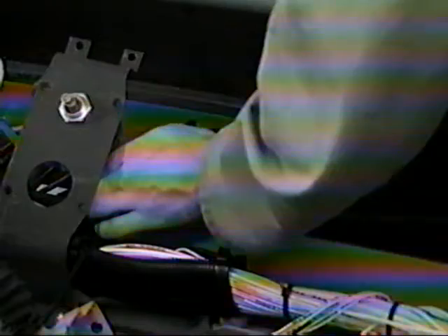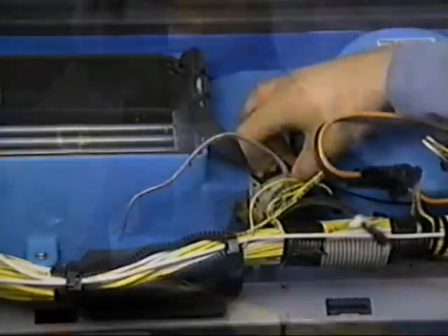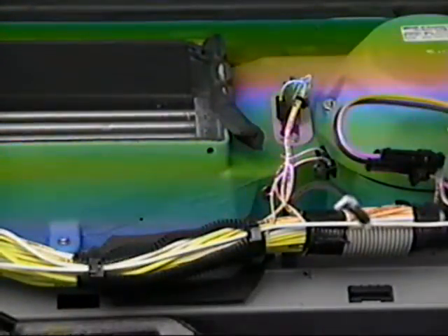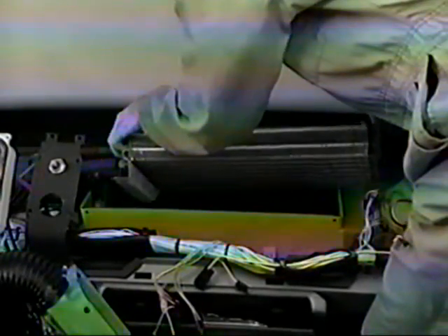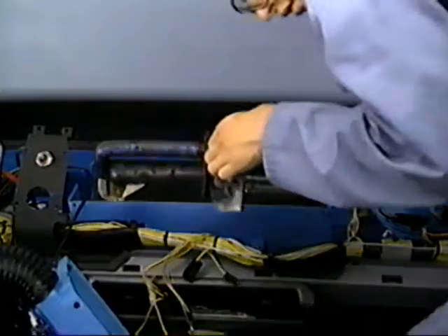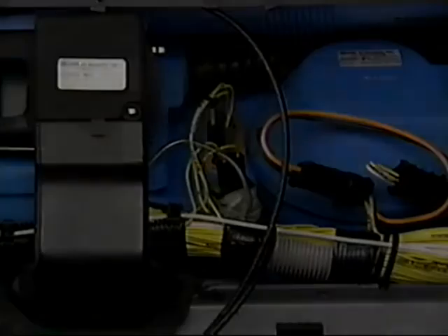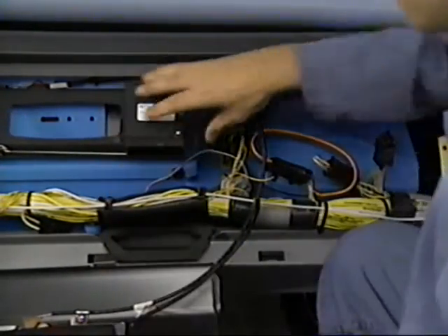Remove the heater core as previously described. Remove the thermostatic switch before removing the AC evaporator coil. The thermostatic switch can be replaced after disconnecting the wiring, removing the 2 screws which attach the switch to the housing, removing the floor transition ducting, and then removing the sensor tube.